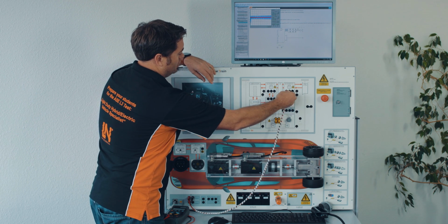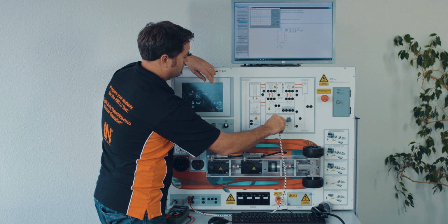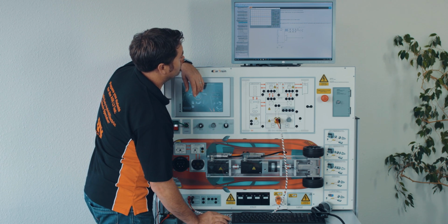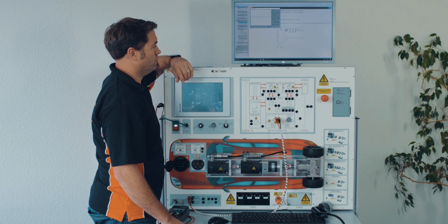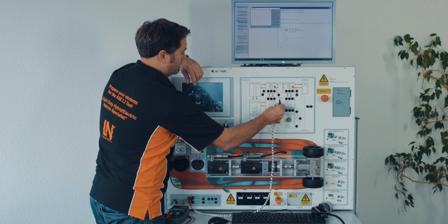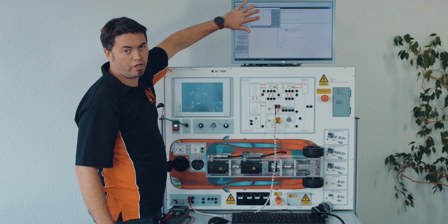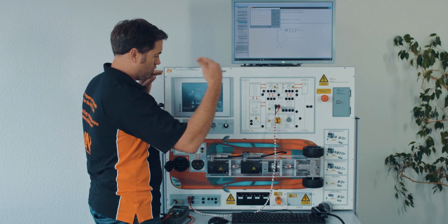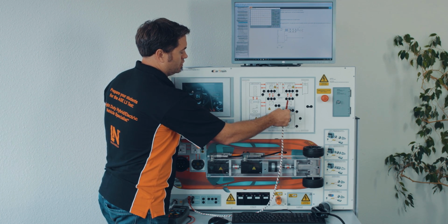We can see here also battery voltage, so I've got a voltage division here of 100, so that's around about 45 to 50 volts. If I take it up the top, you can see here over 300 volts. So this system has the buck boost converter, converting it to a higher voltage.